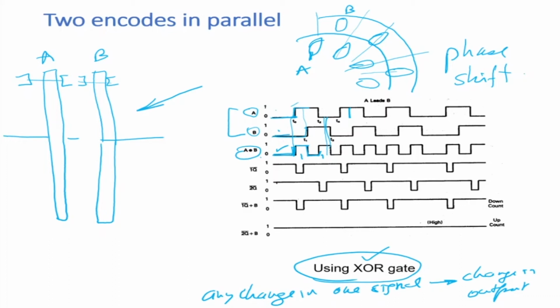So in an industrial robot, the encoders have like 1000 counts per turn, or 500 counts. CPT means counts per turn. That means how many holes are there. So 1000 CPT is pretty high, so it is 360 divided by 1000.